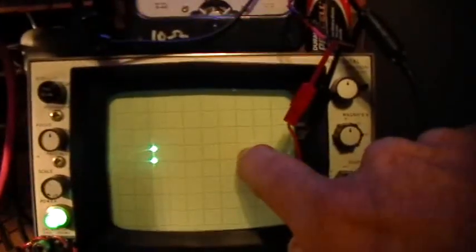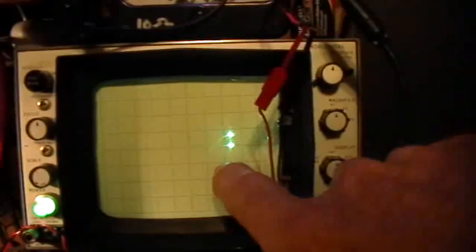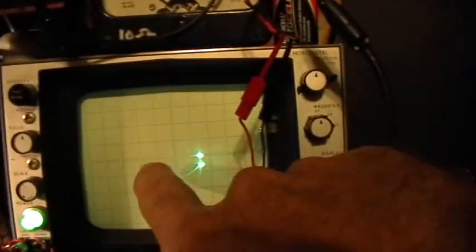Now we're looking at that at 5 volts per division. There's no attenuation. So we're going up to about 3 volts to turn the LED on, and we're going down to about -6 volts. Now if the LED wasn't there, you wouldn't see that voltage drop at the top, and it would be a symmetrical plus or minus about 6 volts, right? But since we've got the LED there, that's using some voltage, some power, so you get a little bit of voltage drop, right?